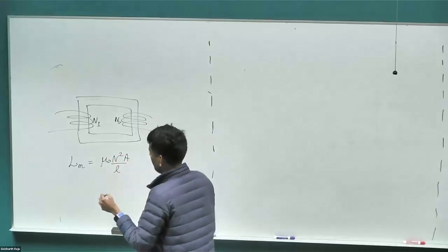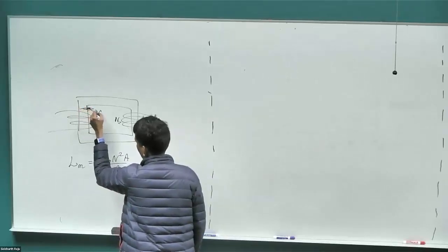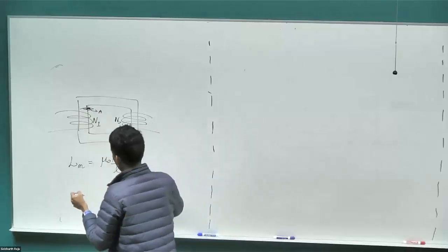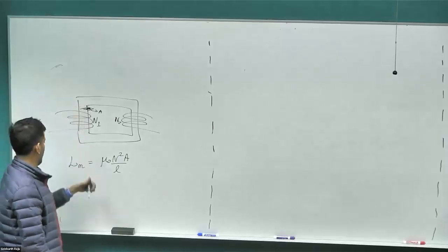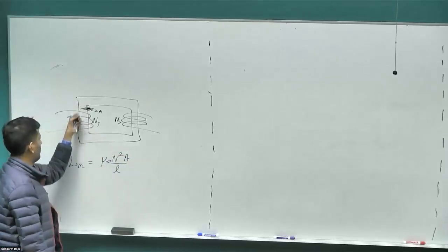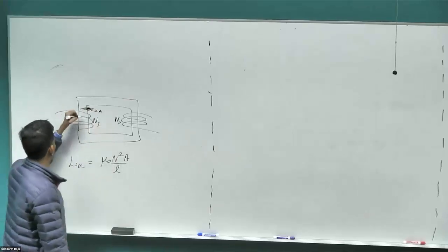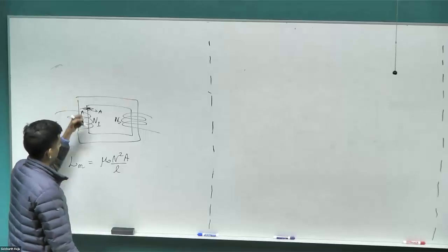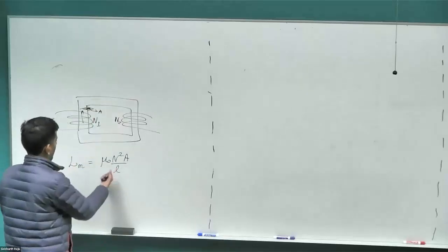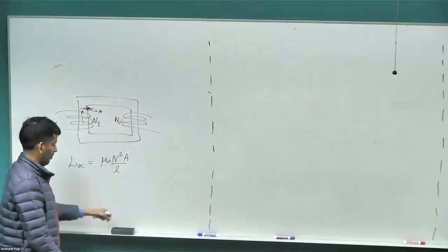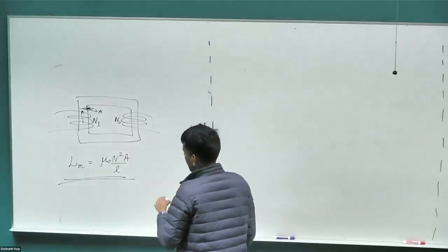This is something we derived in the magnetic circuits lecture, right? Where A is the cross-sectional area. I wouldn't even call it a derivation, it's quite straightforward. You pass some current, you're going to get some flux, and the MMF is going to be N times I, right? And then this flux is linking N number of coils, that's how you end up with N squared. And with the cross-section, you'll get some B, and then the B multiplies with the cross-sectional area to get the flux. That's why you get your area, right? And then the MMF would be divided by the length, the total mean length of this core, right? So this is going to be the inductance of our transformer.